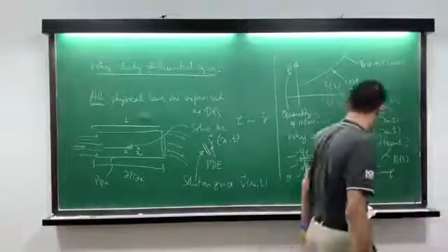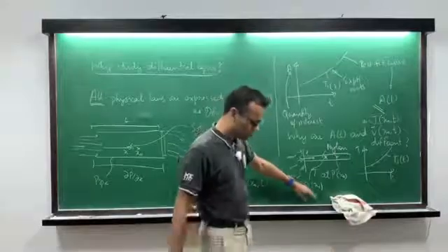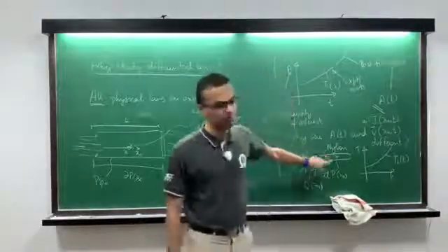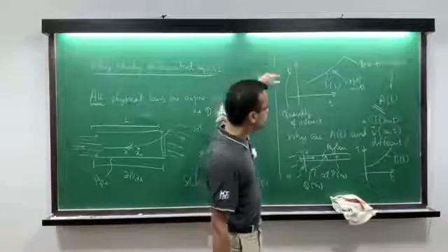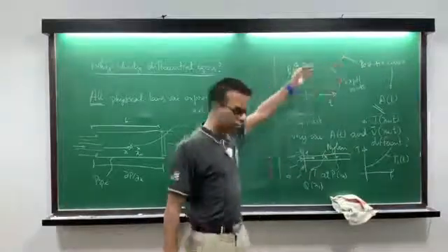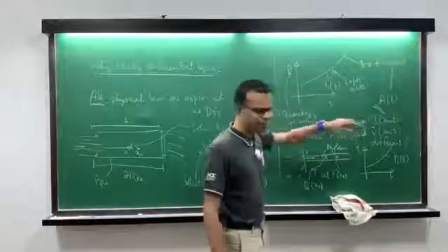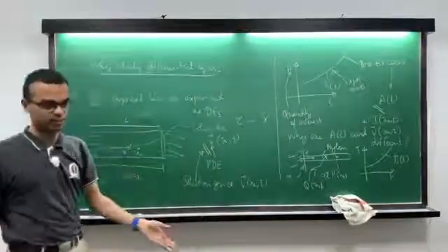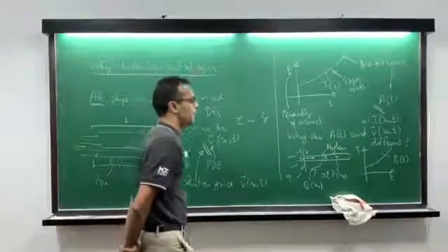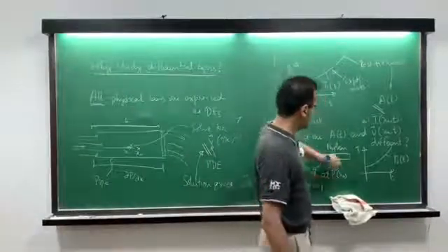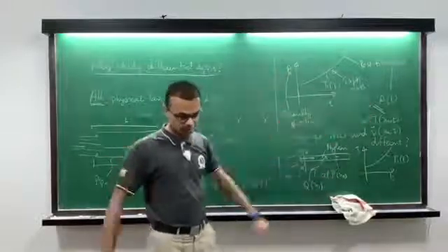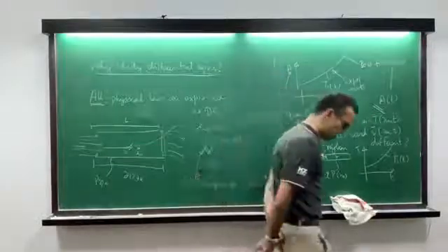Well, you come back and say, okay, Q at a distance x1, let me first do it for aluminum. I'll put a thermocouple here, I measure the temperature, I do a best fit curve, I'll get another curve, and then I come back, I change it, and then I put copper, do the same thing, and change it, put nylon, do the same thing, 3 more experiments. I'll get in total 3 curves here, aluminum, copper, nylon, 3 curves for this, aluminum, copper, nylon, I have 6 curves.